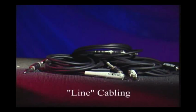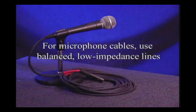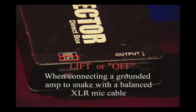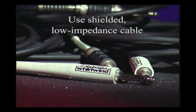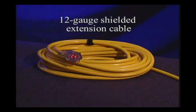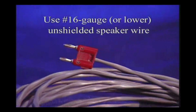The second area of consideration is the cabling used in the audio system. For mic cables, use balanced low impedance lines. With a direct box, the ground lift switch needs to be in the lift or off position when it's used to connect a grounded musical instrument to a snake using a balanced XLR type mic cable. If the stage amplifier uses only a 2-prong AC plug, generally leave the DI switch in the ground or on position. For line level cable, use shielded low impedance cable. For power extension cable, use 12-gauge shielded extension cable. For speaker cable, you can use number 16 gauge or lower unshielded speaker wire.